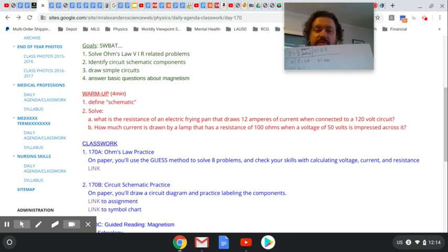We can write it in a bunch of different ways to solve for any of these three variables. Here's a common one. I always memorize this as just V-I-R, and then from there I can flip it around, rotate it around to get the other stuff. Okay, we want to know resistance. We know current and voltage. So if we want to know resistance, we have to get this by itself. And so that means this has to go where the current is, and the current has to go down there. It's kind of the flip-flop thing you do with fractions in algebra.